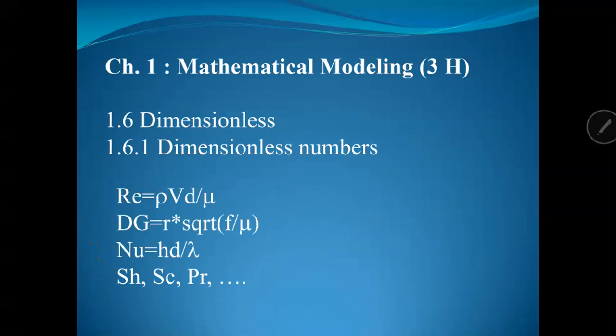Dimensionless numbers. The dimensionless number or dimensionless equation is used to write the partial differential equation in general forms by eliminating all the units and by making the dimensionless numbers appear. Understood? Good. Clear? I don't keep the units. Instead of having rho alone, Cp alone, the viscosity, the density, the diffusivity alone, I put all these parameters together